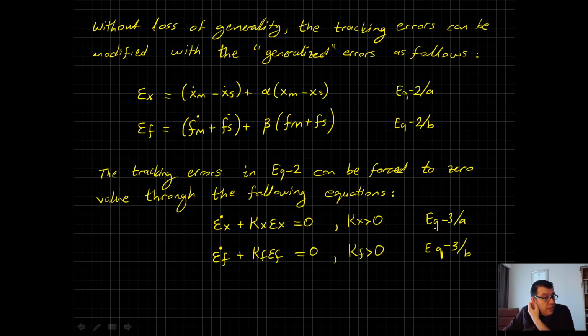So far so good. Remember what we were doing. We were basically taking this error and substituting it into the error dynamics, trying to formulate a big algebraic equation from which we can extract the desired accelerations. And we're gonna stick with the same methodology here because that's the same way of deriving the controllers.